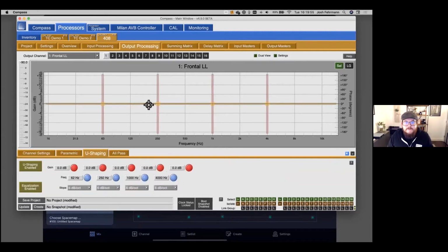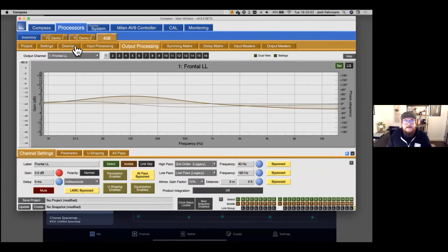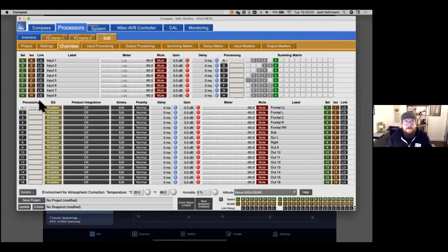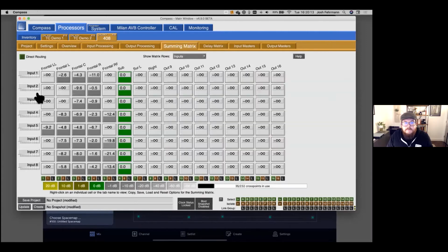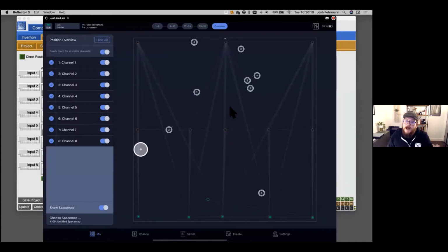Well, I can still do all of the loudspeaker processing, and EQ and delay and parametrics, all of the things that are included in here. I could still tune my PA. And now with this free update, all I do is put my Galaxy into Spacemap mode. And I'm just using Spacemap Go to control the matrix level using the Spacemap Go algorithm, which is a custom algorithm that we've had around for about 30 years that makes immersive audio and panning very, very easy and very flexible.